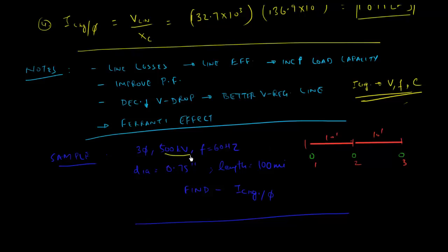So you should see an effect here. The voltage has been raised up. Also, the length of the line has been increased. So in effect, you're changing the capacitance because the capacitance is distributed evenly along the transmission line.